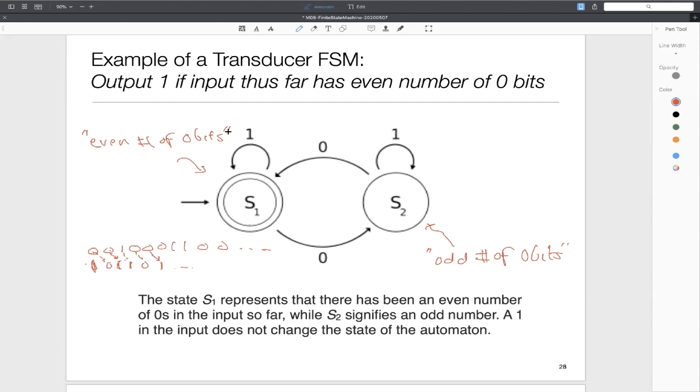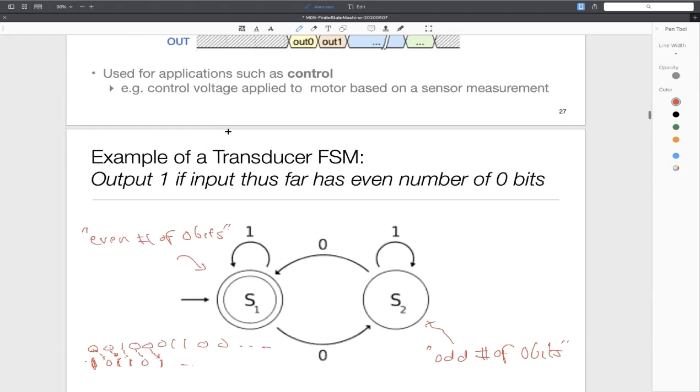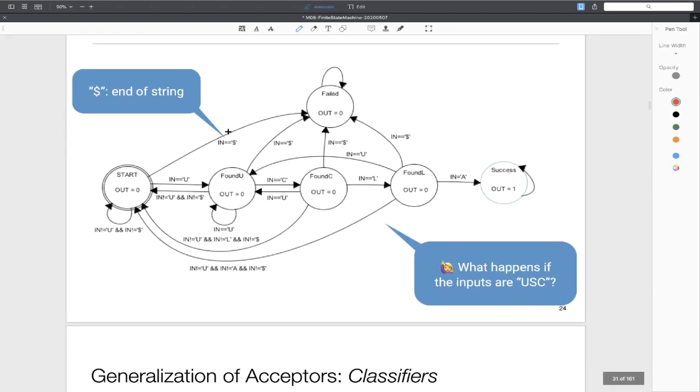No, so the thing is that the classifier at some stage ends in a state and stays there, right? Because it terminates. At some stage it would say, okay, I have recognized which class it is in, accepting, rejecting, or remainder 0, 1, 2, 3, and then it will output. Even though there will be bits coming at the output of the hardware, because after all it's hardware, those bits don't necessarily carry any meaning. So if you look at the state machine for that example, you would see states where I reach that state and I never get out of them, because I have done the classification.